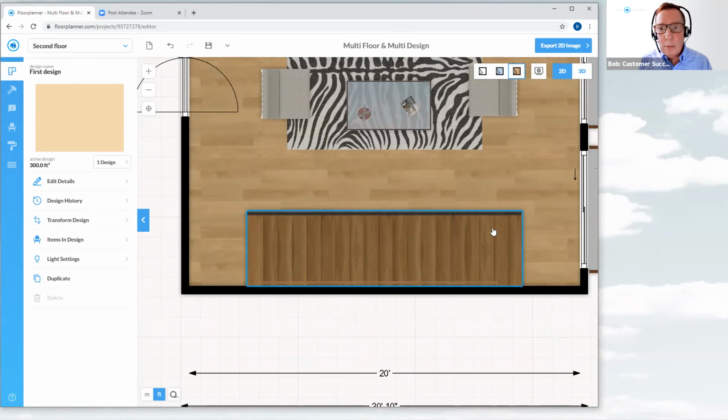And I know that when I make an opening, it's not going to be as long as the entire staircase because your head will clear at some point. So if you know what that dimension is, that's great. But I'm going to show you how to actually do a cutout in the floor. And then we're going to delete this staircase that's sitting on the second floor because we only need the one staircase from the first floor.